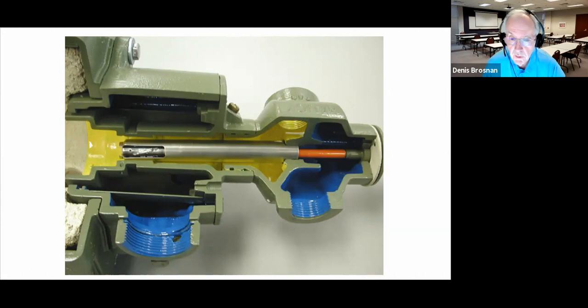to oil and the gas supply is shut off, then we have the oil coming in here as indicated by the orange. There are perforations in this pipe. The shroud around it contains the oil vapors. You can see some of the perforations in the pipe here. It's been cut away just for demonstration purposes. This is injected into the fuel area of the burner. And of course, the air to sweep the oil vapor is coming through here. Dual fuel burner, the oil would be a backup fuel in this particular situation.